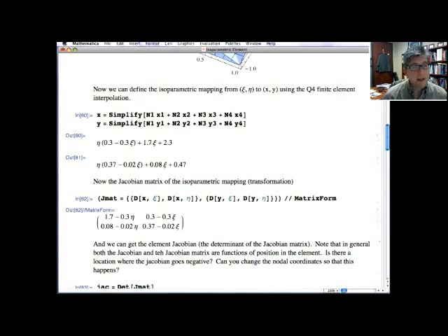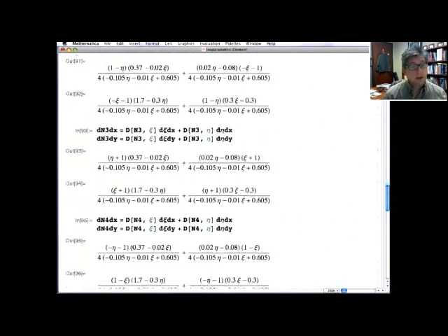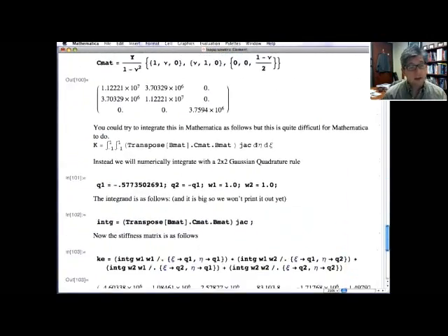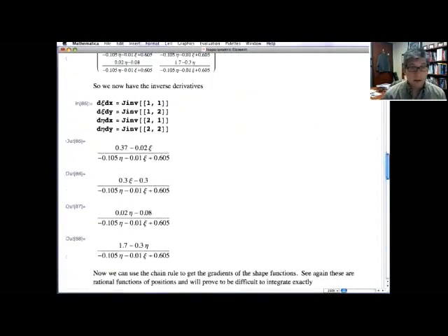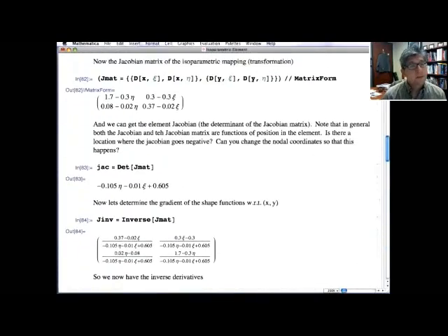Now, normally, at this point, we would actually do this at a particular psi and eta point, right? Because we're using this information just to determine the value of this integrand down here at a quadrature point, right? So B, this is what we're really trying to get, is B, right? So that has to be at the 4 quadrature points.